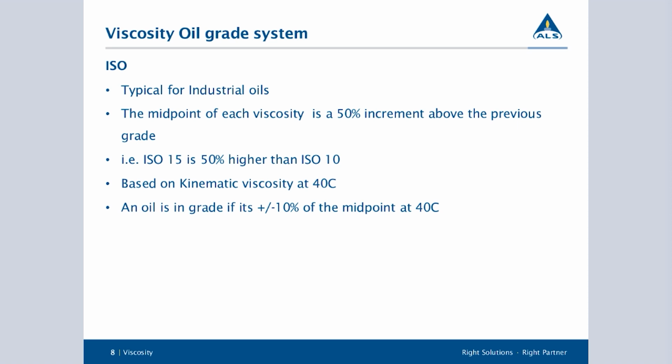But your engineer should understand roughly what you're dealing with in terms of pump size, gears, and other components that are required for these different viscosities. And so what you'll see when they're selecting one is that for slow moving gears, you want a thicker oil. And for oils that are too thin, they don't provide adequate protection. And then for gears that are very small and very fast, you want more of a thinner oil. This is like your hydraulic pumps or even oil-filled bearings. And so what you typically see is that your ISO 32s, 46s, and 68s are used in bearings and hydraulic applications. Your ISO 150s and 220s are often your indoor gearboxes.